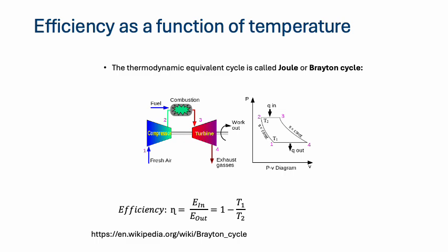But we cannot change T1 because it is the air in the outside atmosphere. It's already pretty cold. If you saw the computer screen while you are in an aircraft, it would say the outside temperature is some minus 30, minus 35 degrees Celsius. It's already low, and we cannot manipulate it. It is controlled by the environment in which it is operating. But T2 is the operating temperature of the turbine. So if I can increase this T2, the temperature resulting from the compression, if I can go to higher temperatures, then my efficiency increases. That's why we need high temperatures.